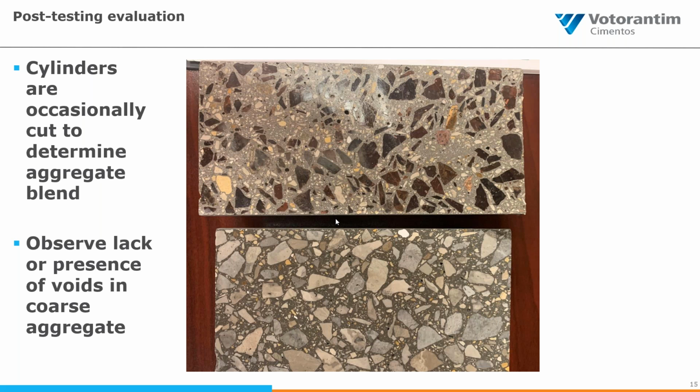When we're producing this type of work, I have our technicians run anywhere from 3 to 5 gradations a week to ensure that we're making any adjustments to maintain those high modulus of elasticity ratings in the concrete designs. But the cylinder on top, I'm going to point out for 2 specific reasons.